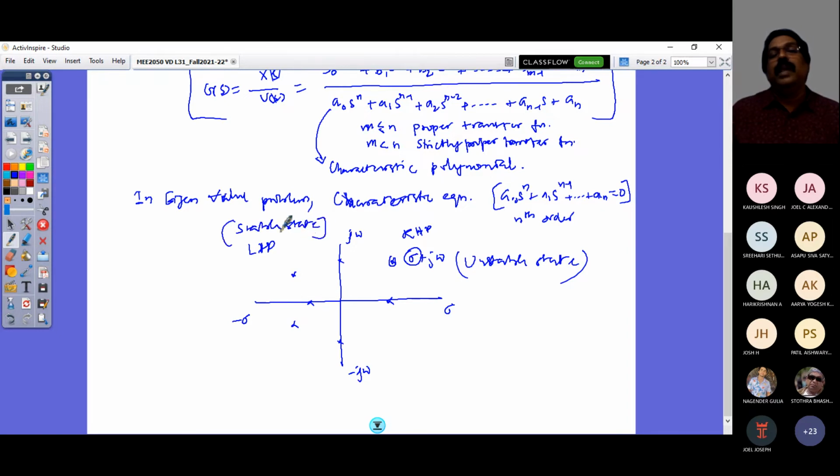So now the question is, here I have an nth order system, I have nth order characteristic polynomial, and hence the characteristic equation, eigenvalue analysis, and find the roots, and the root finding is going to be tedious. So I can have roots which can be linear, quadratic roots, or higher order roots. So I can partially factorize them as a linear factor or quadratic factor or cubic factor and so on, and then simplify them and find the roots. So it's a tedious process, finding all the roots and then commenting on the stability.